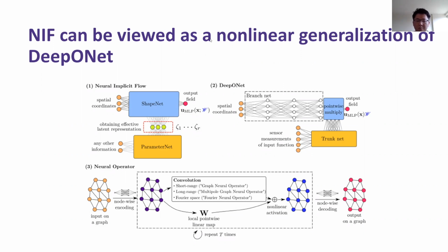The sensor values could correspond to maybe five equally spaced locations on the boundary, and you get the temperature values at those 5 points. Maybe it's a good approximation of the temperature profile on the boundary, and you can put that into the parameters. And if you change the boundary condition completely, do you still have valid solutions? It depends on the nature of the problem.